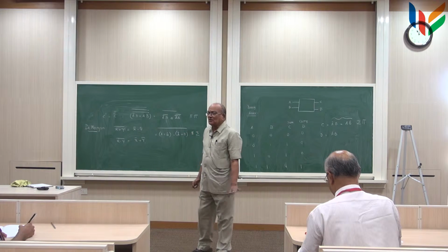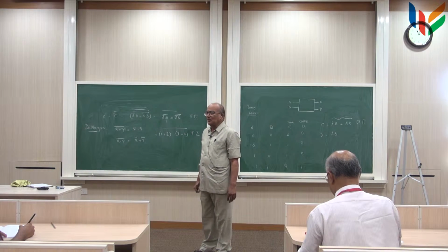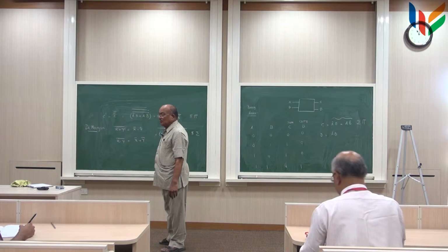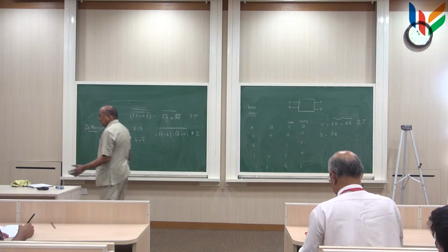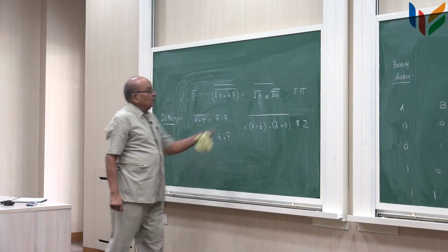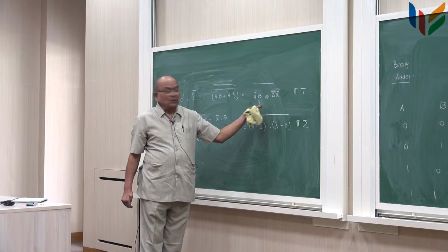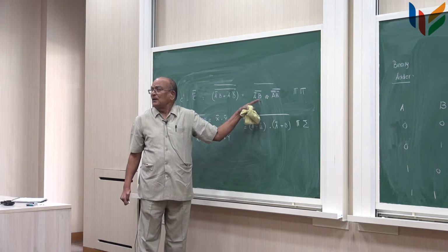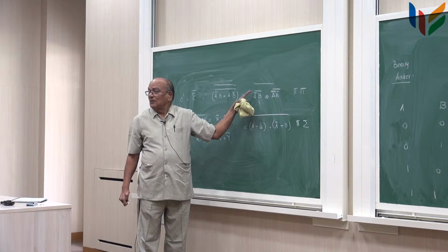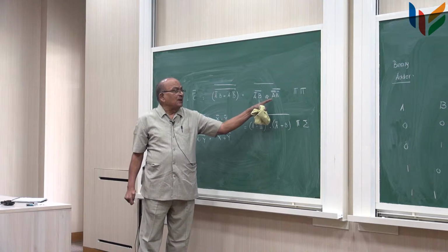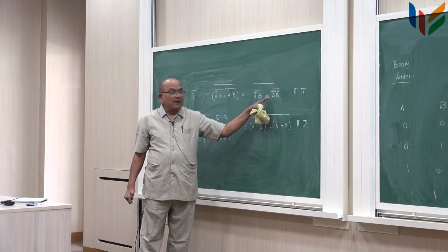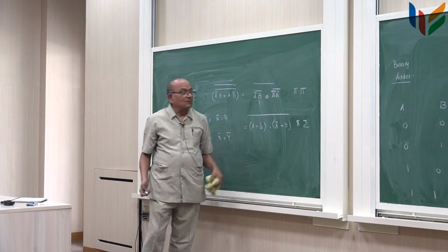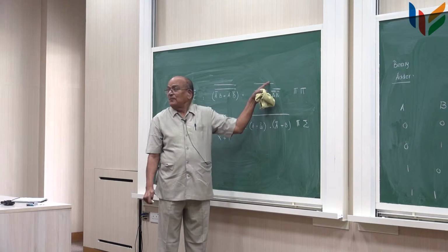So by applying the De Morgan theorem on the Boolean function, you are in a position to convert into any one of the forms which may be suitable for you for some particular application. You look at this, what does this say? This says A bar multiply by B bar and take a complement of that, and similarly take A and B bar and AND it and take a complement of that and put them into another AND gate and take a complement of that.